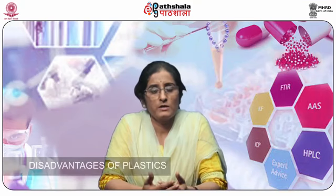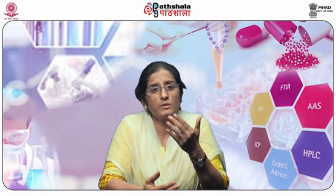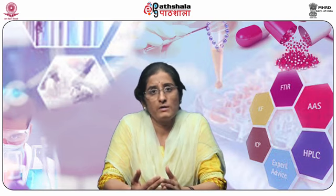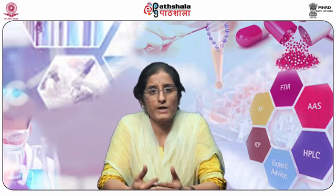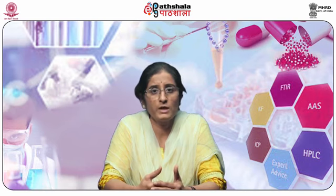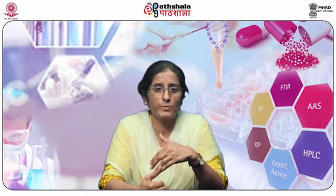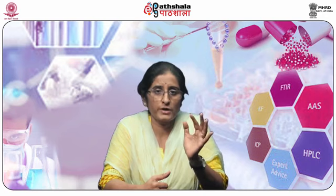Disadvantages of the plastic. Now let us see what are the disadvantages or the limitations when we are using plastic as a packaging material. The main disadvantages are that they can allow permeation, and it can occur in two directions. Two directions means from the solution or the formulation in the container through the plastic into the ambient environment, and from the ambient environment through the plastic into the preparation. So in both ways, the product is going to be degraded or affected.